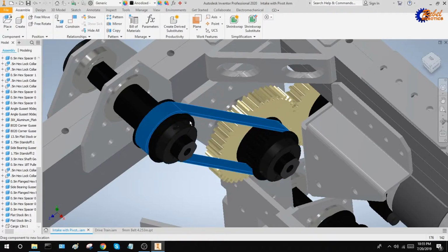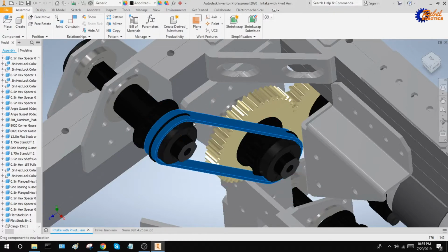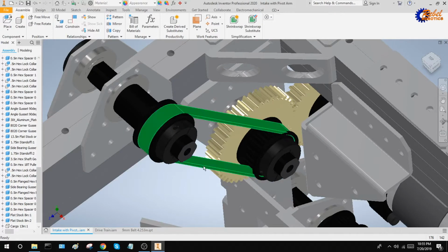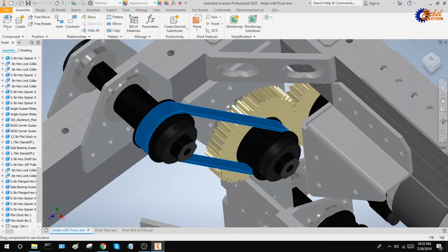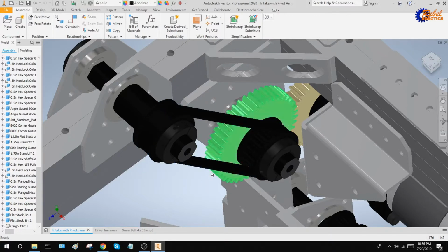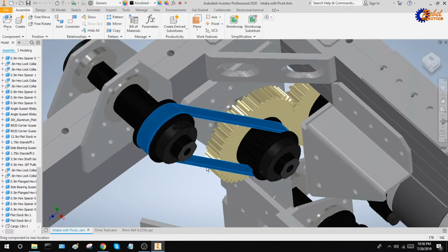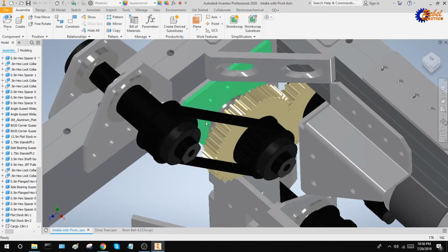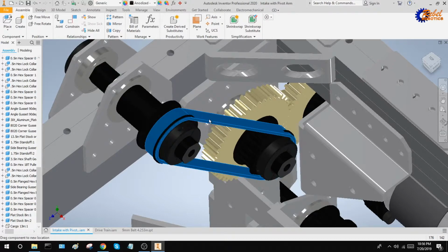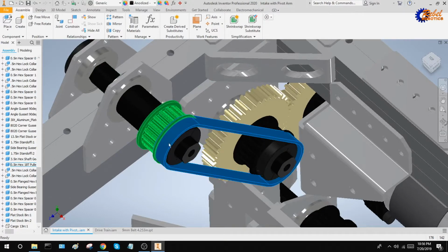For belts and pulley and chain and sprocket setups, it's very difficult to get the exact right length for the chain or the belt because the geometry makes the numbers very long and irrational. So just use a rounded number for your length, then just use a constraint with a maximum to give yourself some leeway so you're not chasing all those digits.